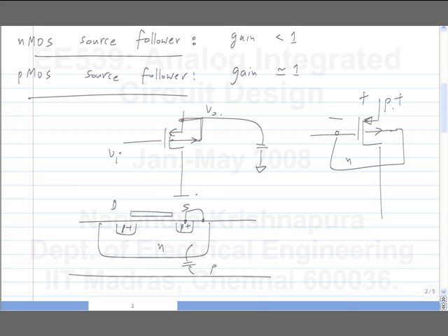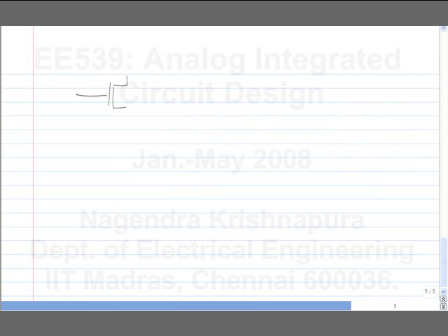When this voltage becomes very small, there are many things that happen when you try to lower the bulk potential in a PMOS. Or for instance, let's say I start with NMOS, and for now I'll assume that I have freedom to tie the bulk anywhere I want. I have the bulk tied to 0 volts, and then I have another scenario where I have the bulk tied to a negative voltage, or thirdly, I have the bulk tied to a positive voltage.